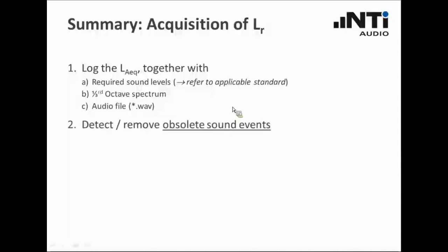Then you should look for obsolete sound events. Let's assume, for instance, you have to monitor a construction site, and then all of a sudden a loud car accident happens, which has nothing to do with the noise from the construction site. So you have to exclude this car accident sound by deleting it or by disabling it in your chart view, to make sure that it doesn't have any impact on the overall calculation because it's not related to your task.